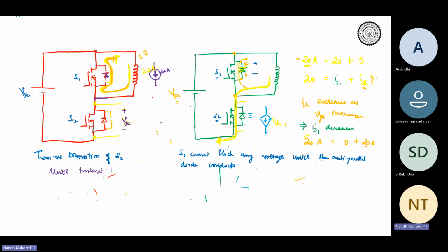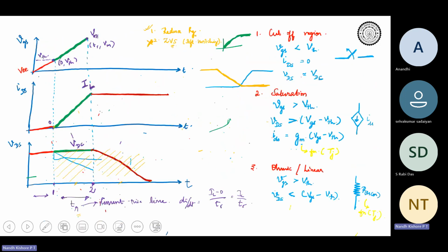In that case, the inductor current is no longer a fixed DC. Since you are operating at a very high frequency, the inductor current actually varies like a sinusoid, and I will make my switching frequency match. Then I will turn on my device near the zero crossing of current, so naturally I will be getting ZVS. This is totally out of scope, just to give you an idea. They are known as resonant converters. That is one way of doing ZVS. There are multiple ways though.